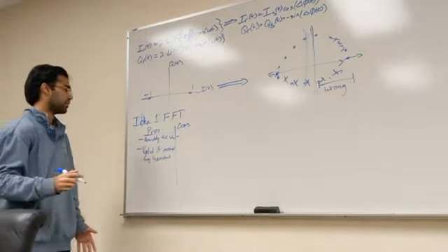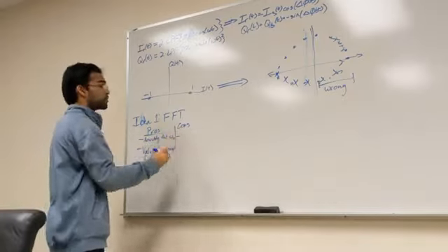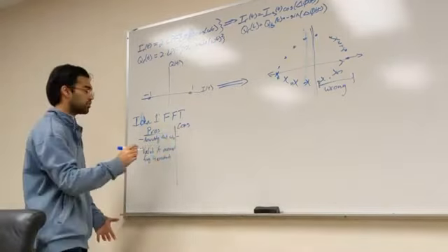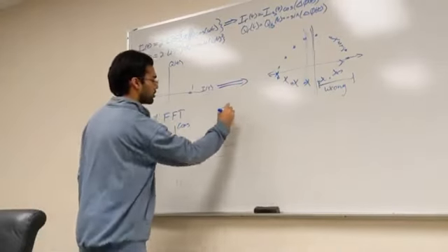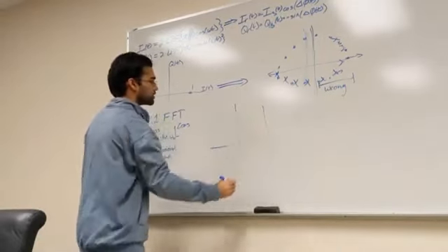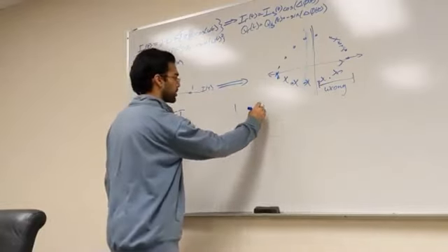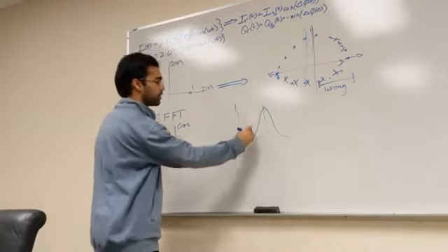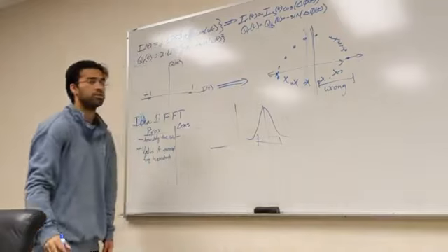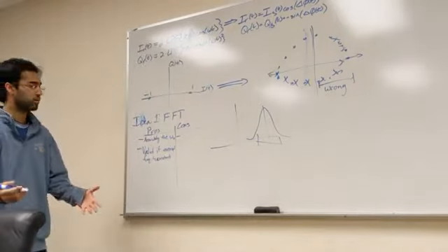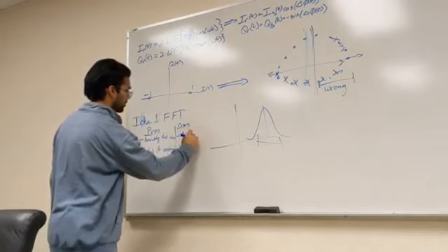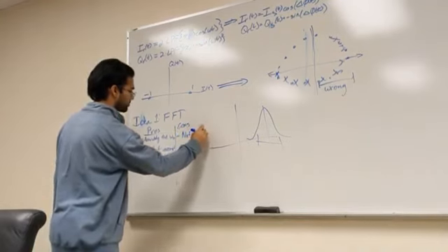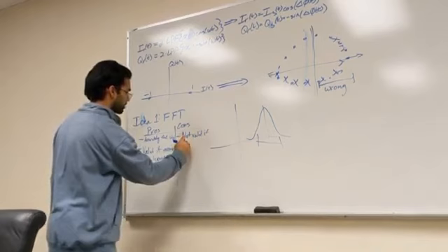It's a trade-off. And so, if your frequency does change, then you don't know it. On an FFT graph, instead of a distinct spike, it'd be more of a gradual spike, like that. And so any one of these frequencies could be the valid frequency for a specific time instance, but you don't know. And so, not valid if frequency changes a lot.